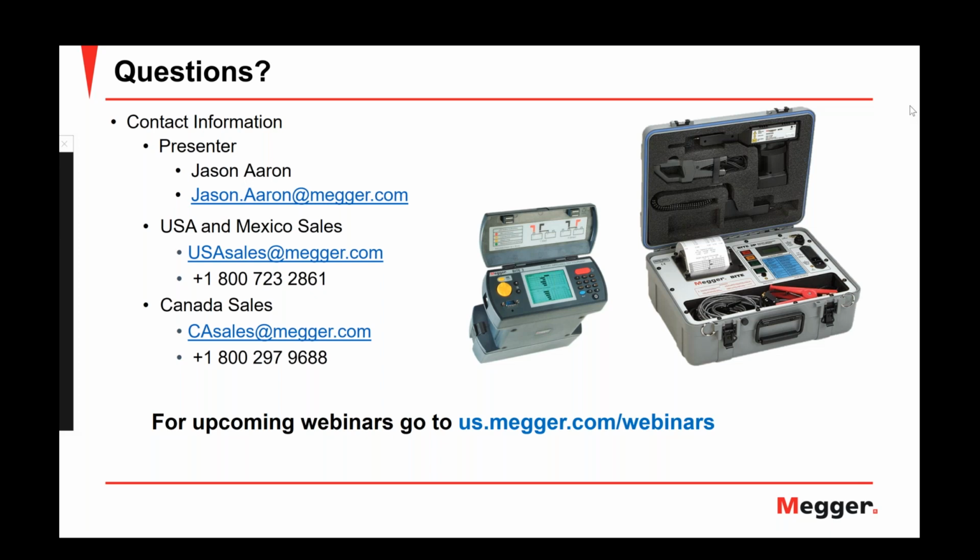So if you know that the battery is going to be in an environment with elevated temperature, you need to discuss that with the manufacturer so they can recommend the best battery or the best product for that condition. Usually, if that is the condition, NiCad batteries are more recommended. Of course, they're more expensive.